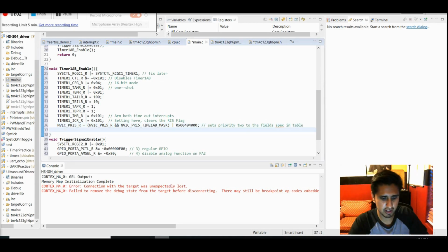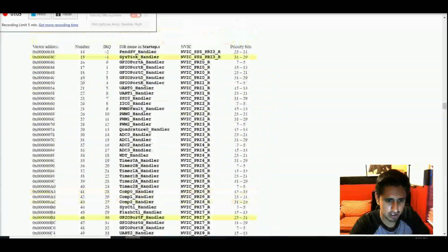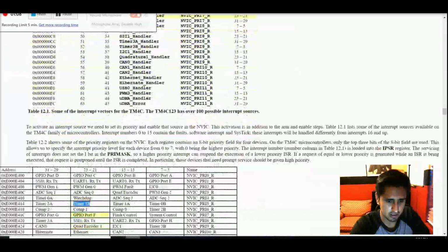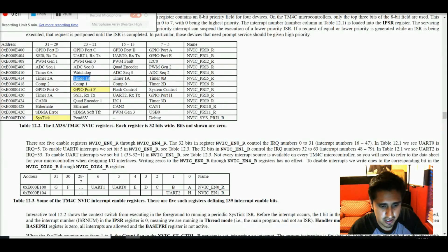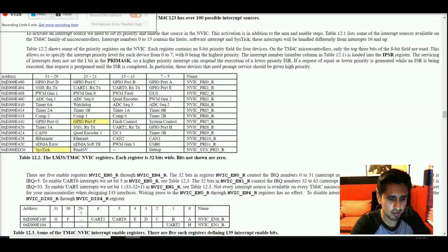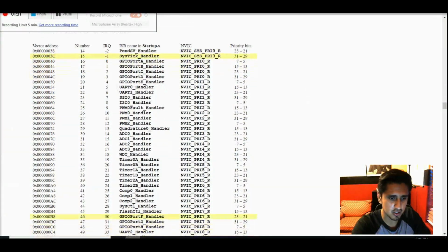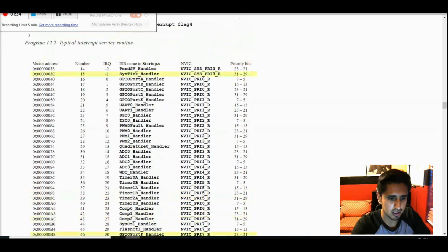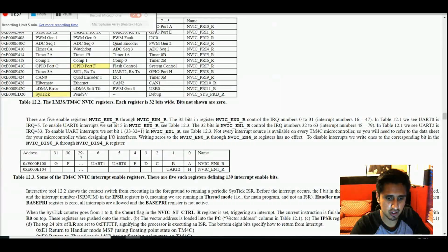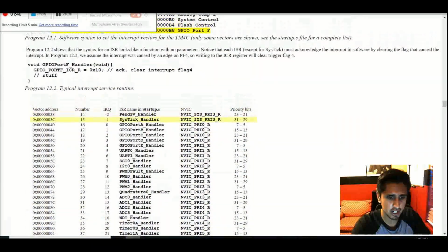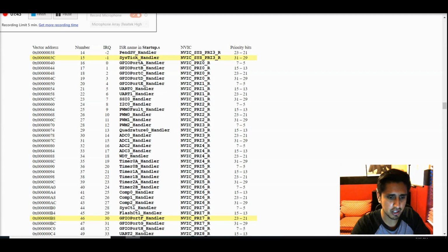So now the last thing on the NVIC end is that we have to look at the NVIC enable register. Pretty much we have to set the bit corresponding to the peripheral of interest. For example, here, if we were interested in setting interrupts for UART1, we would set the 6th bit to 1 in this register. Where does this number come from? That's a good question. That number comes from this interrupt IRQ number. That's the reason why there are two 32-bit registers, because there are 50 of these entries, but only 32 bits, so we need 2 of those.